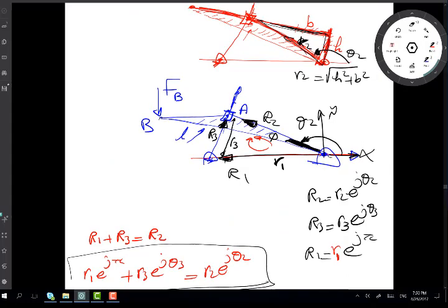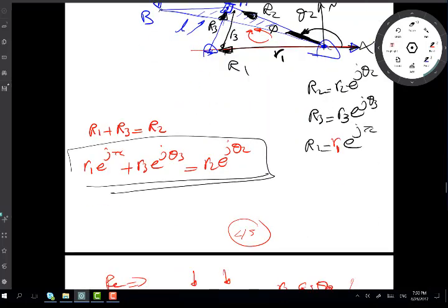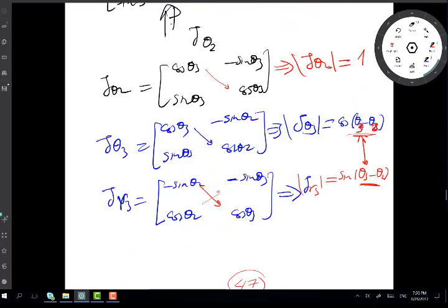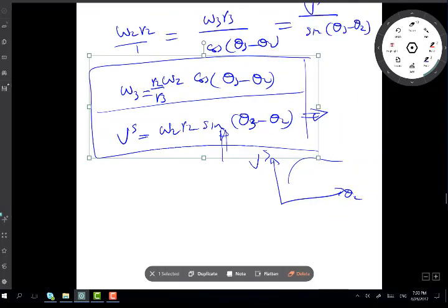So that's really more of a control problem at this stage, because you feed whatever pneumatic air or hydraulic fluid into this via a control system, some directional control valves and pumps, just to give you the rate of extension that will make omega 2 happen at this specific value. And this rate of extension is a function of the angle of the tray as per this equation, right?